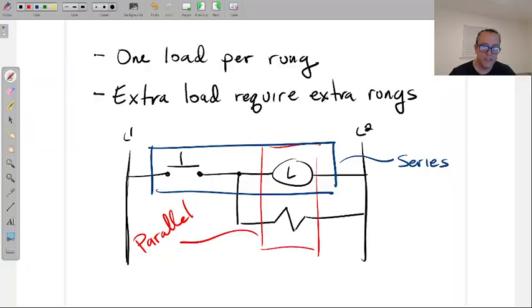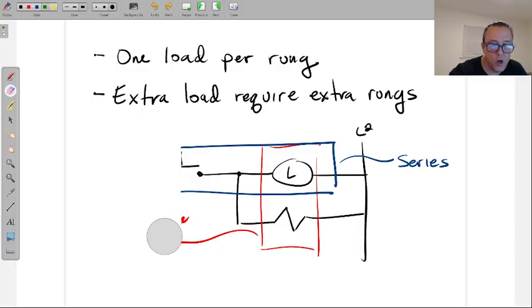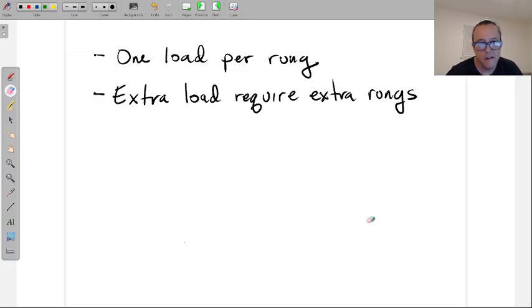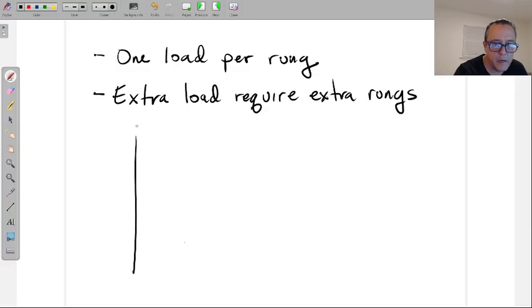But let me give you a for example of when they're not. Here's when they're not. But let me go back 1 second. The reason why they're in parallel with each other is because of the fact that we are picking up this rung from the same rung that is feeding that light. So in other words, we're picking up the rung for the solenoid from rung 1. We'll get into the numbers of the rungs. Not too complex. 1, 2, 3, 4. We just count in that order, but we'll get to it. It is going to be coming up as a note here in a second.